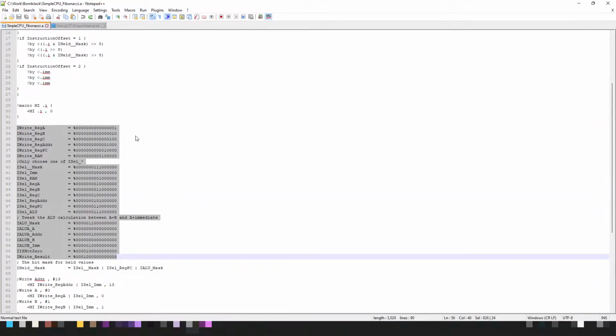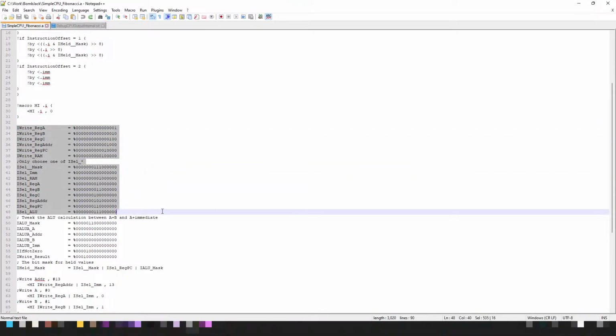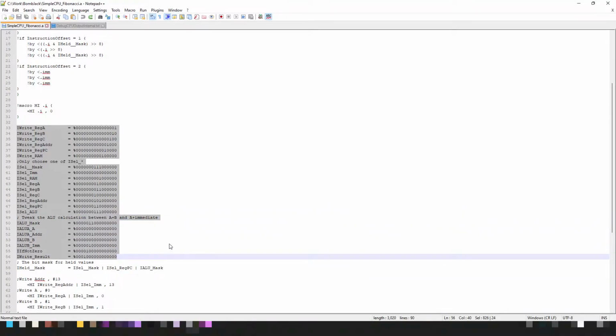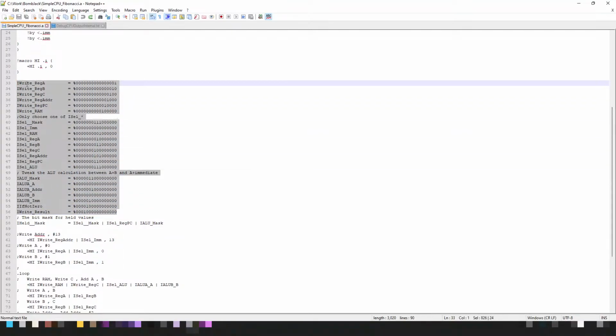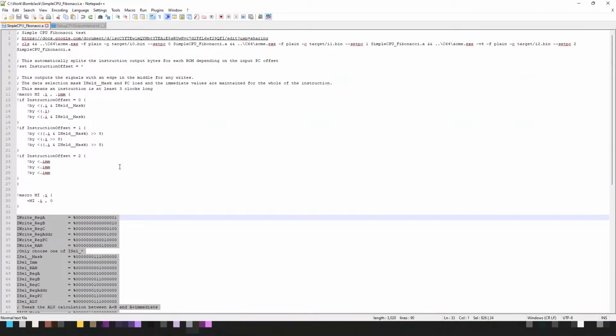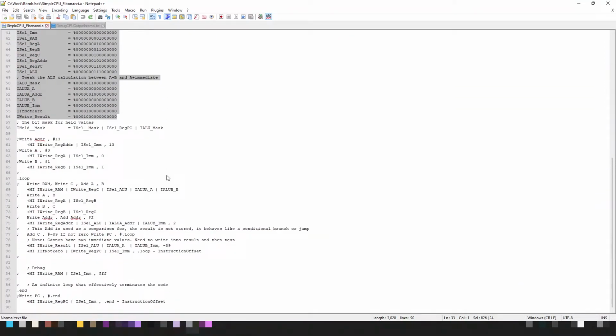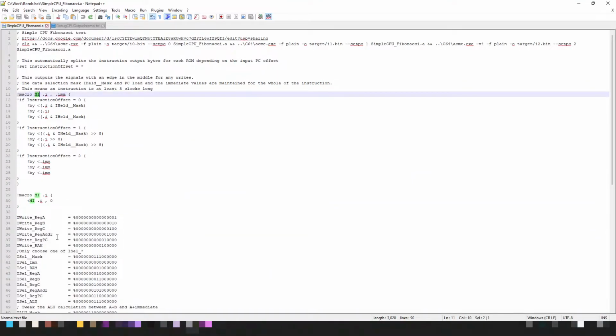Well, it is 24 bits wide, because I know that I'm using, say, 12, rounding it up to the nearest byte. I'm using 16 bits to represent the internal states. I have 3 more bits available here, but I'm basically using 16 bits for the internal state registers, and then another 8 bits for the immediate value storage. So that's why the CPU uses 3 8-bit program ROMs, and that's why it's 24 bits wide in terms of each instruction state. Okay, now the instruction itself, the MI macro, can optionally take an immediate value.